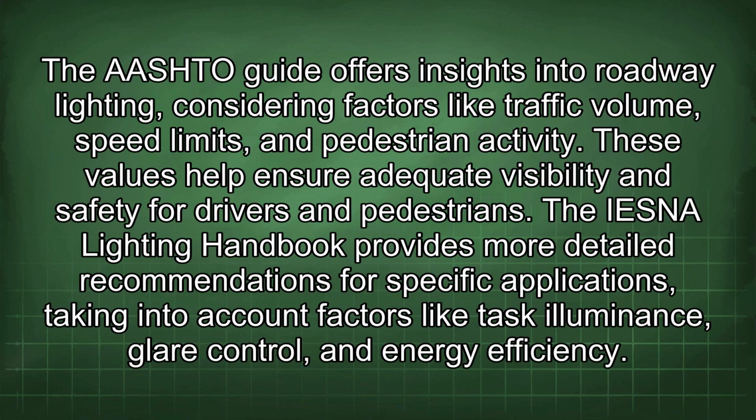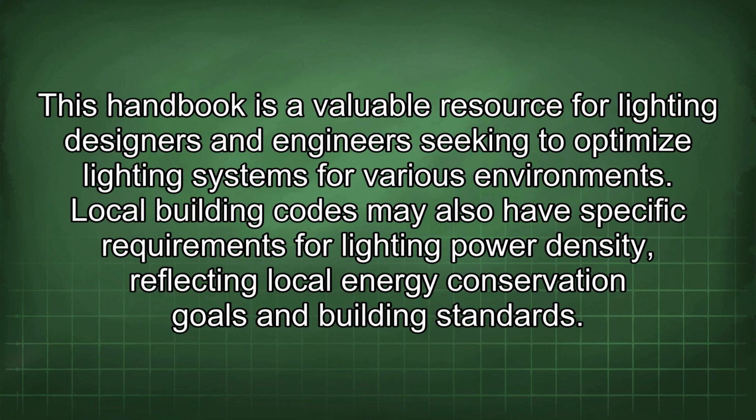The AASHTO Guide offers insights into roadway lighting, considering factors like traffic volume, speed limits, and pedestrian activity. These values help ensure adequate visibility and safety for drivers and pedestrians. The IES Lighting Handbook provides more detailed recommendations for specific applications, taking into account factors like task illuminance, glare control, and energy efficiency. This handbook is a valuable resource for lighting designers and engineers seeking to optimize lighting systems for various environments.